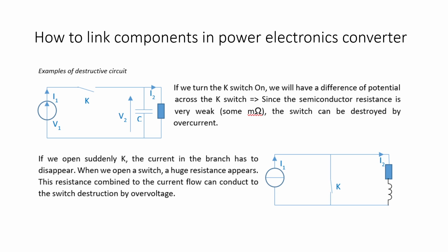And another thing, you need to be careful when you connect a storage element with a source. If you have a voltage source, this one a current source, please avoid connecting like this. You avoid parallel between source and capacitor. Parallel between current source and capacitor. Why?